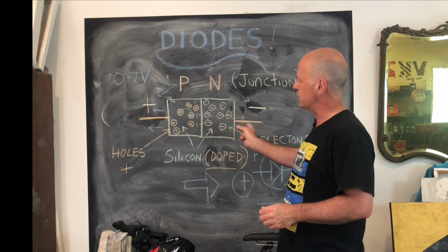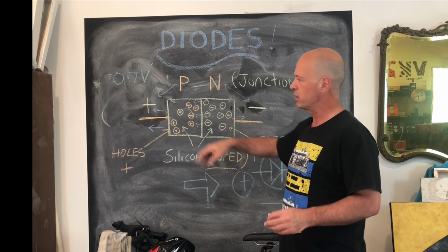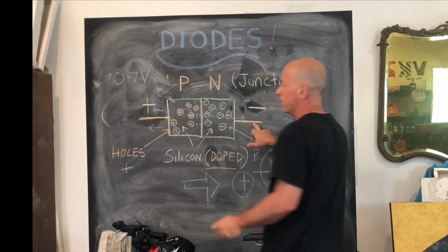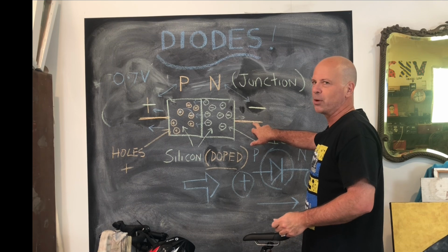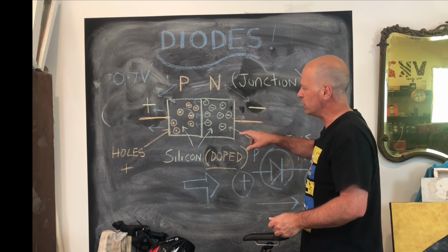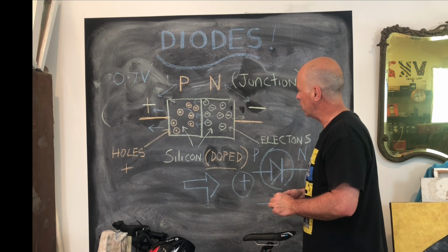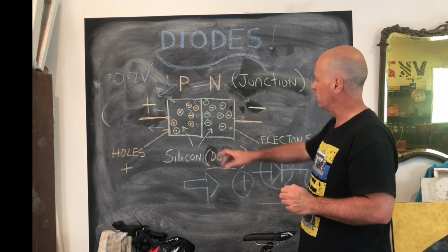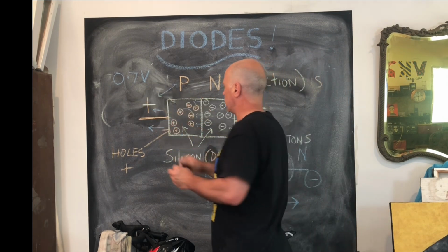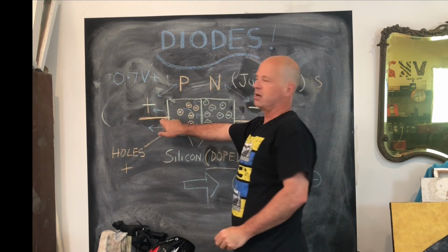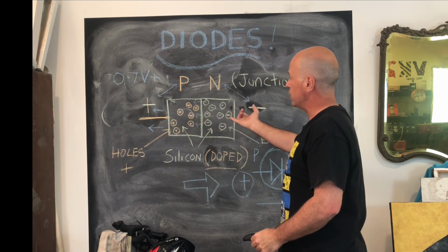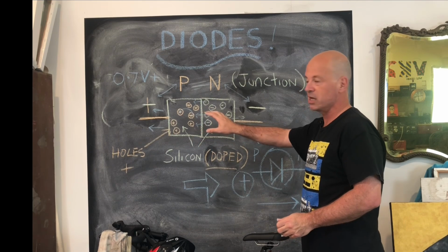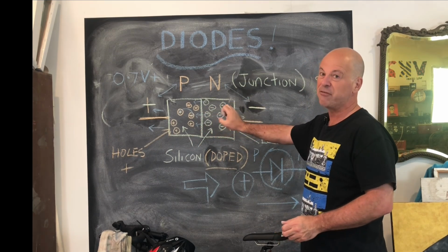So if I wanted to check to see whether this diode was conducting and whether it was okay, I could actually put positive here and negative here and just see whether I get a 0.7 volt voltage drop across it. So it's a really good way of fault finding as well. But basically what you need to know is that it will allow current to flow once we get to 0.7 volts positive on this side. If we reverse the polarity, it shouldn't let voltage flow until you get to hundreds and hundreds of volts, in which case usually the component has failed.